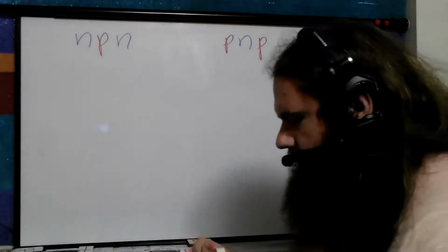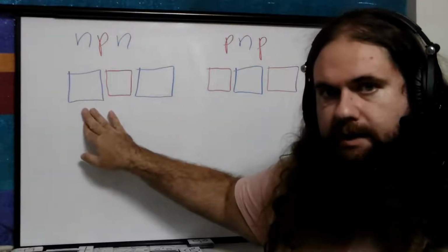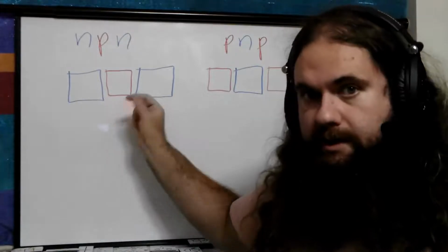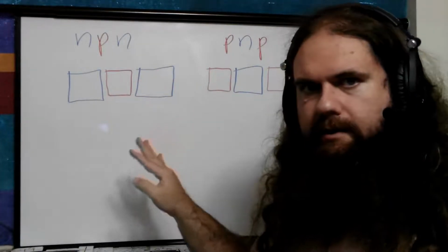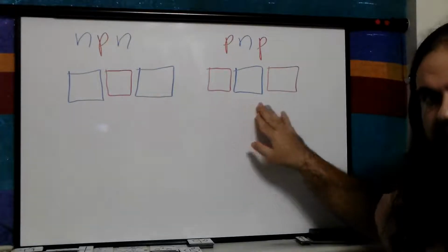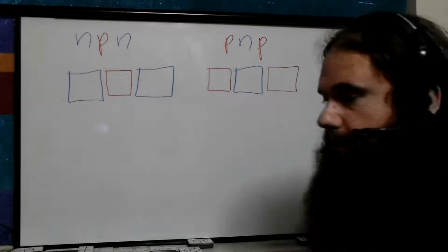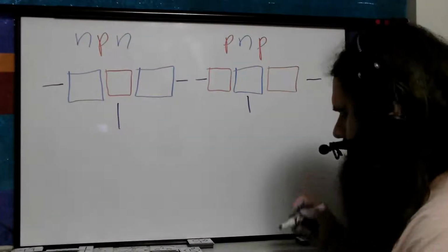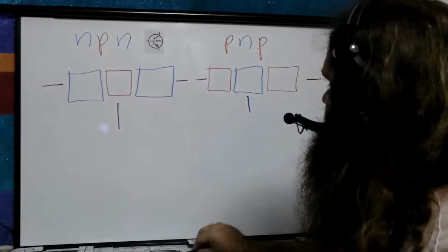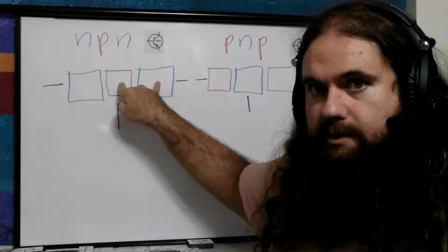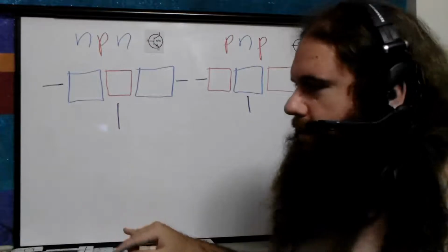This is just 3 layers. So unsurprisingly, you have an N material, a P material, and an N material, all touching. The P is usually smaller, but that doesn't matter. Don't worry about how they're constructed. It's just these 3. PNP is just the opposite, a P, an N, and a P. They all have 3 terminals. So this is an NPN transistor, and this is a PNP transistor. And these form depletion layers just like the other. It's just trickier how it works.